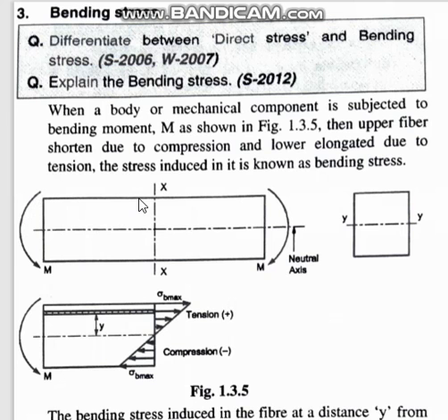Suppose that pulley in the center, along with the load of the bucket and water, is pulling it down, and in the middle there is a rod, supported at two ends. Because of the central load, it tends to bend a little. So what is it doing? It is inducing bending stress there.